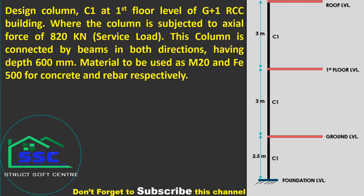So here we have to design column C1 at the first floor level of a G+1 RCC building, where the column is subjected to an axial force of 820 kilonewton, and this force is actually service load. Here I am expecting that you are all well aware of service load and factored load. What is meant by service load and factored load, I am not going to discuss these things.